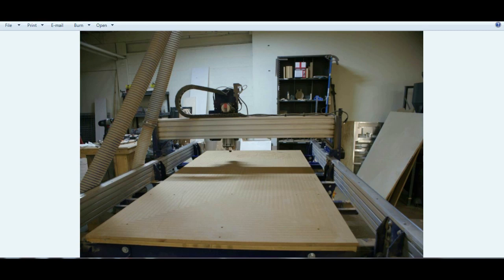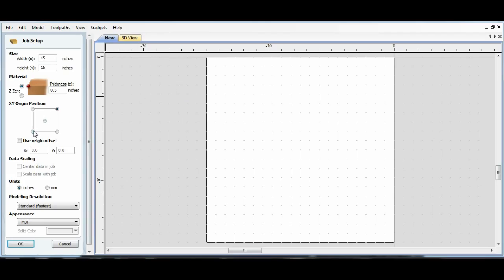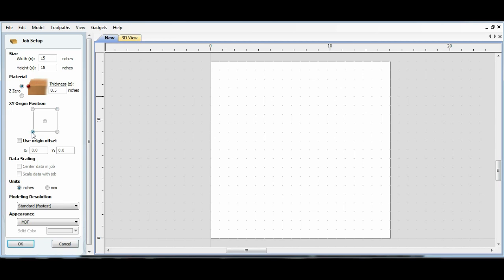So it is very important that until you know better, for whatever reason, make sure you know what you're doing, but make sure it's bottom left. I say that because people come in and use this machine right here, use PartWorks to lay out their files, and I don't know why, maybe it defaults with PartWorks to be in the center. Just make sure it's bottom left.